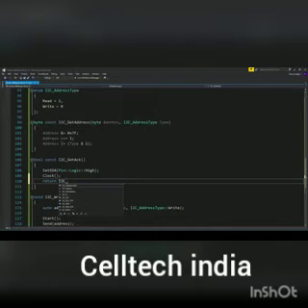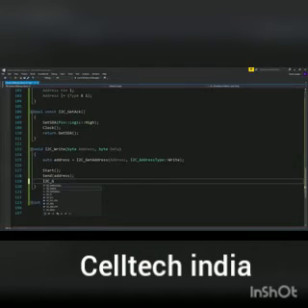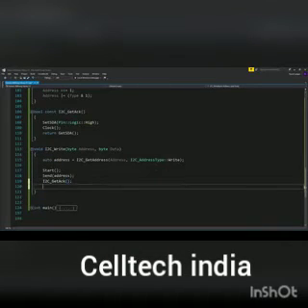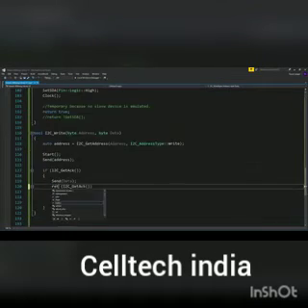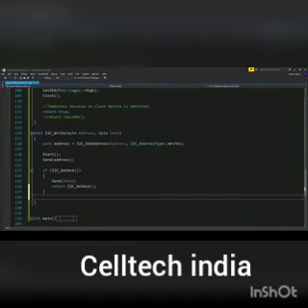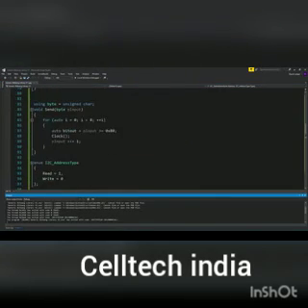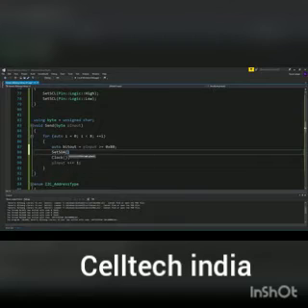We also need a function to get an acknowledgement, and an acknowledgement is basically allowing the data line to go high and then clocking and reading the data from the slave, and that's what we have here. Now if we don't receive an acknowledgement, we do want to abort the write routine, so let's check if we received an acknowledgement and then figure out what we're going to do with that. I think I'll probably just return true if it's successful and false if it's not. Okay, so I've got to make sure that I'm actually setting the output. That's the SDA, so let's call a function that gets that bit out of temporary and sets the pin.